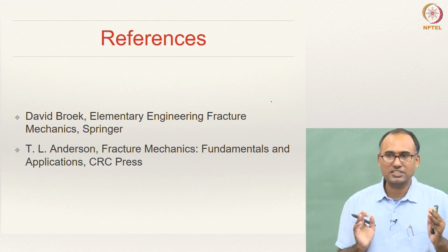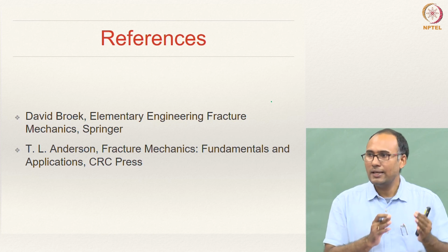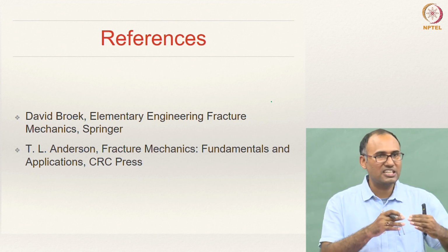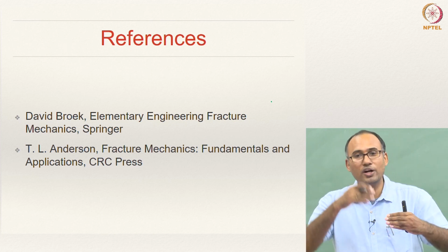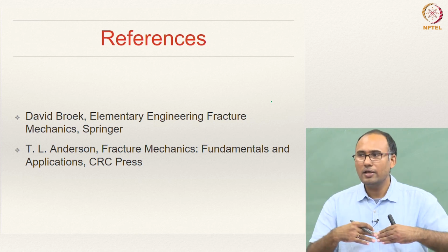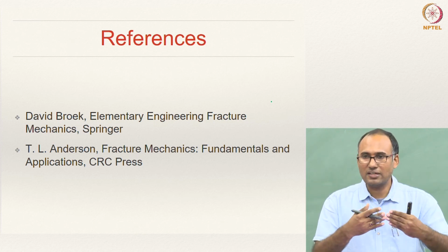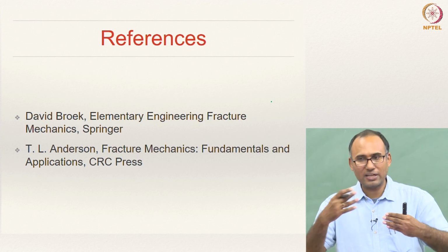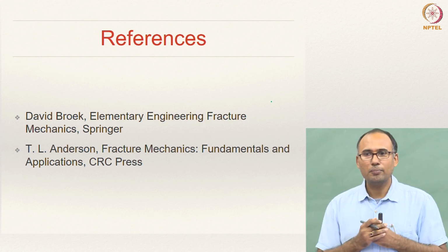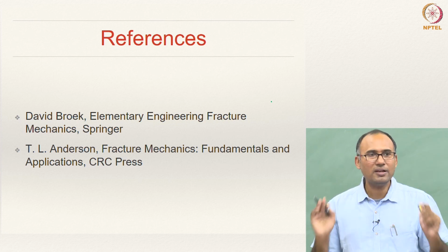Both are equivalent. Whether you say the crack propagates when my energy release rate goes beyond the critical energy release rate, or when my stress intensity factor becomes equal to or greater than the fracture toughness of the material, both of them are equivalent.